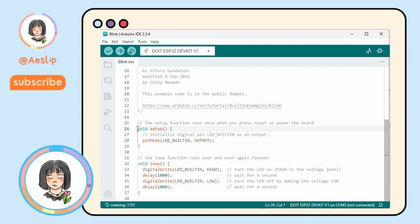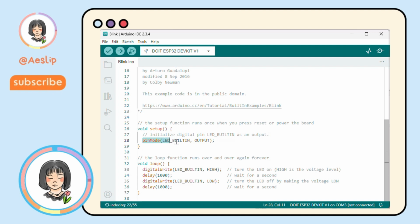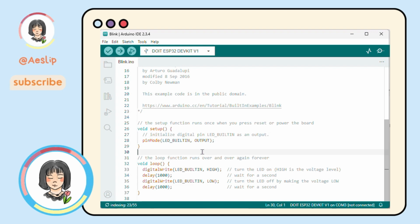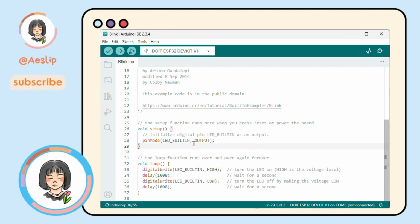First is the void setup. This function is called once when the program starts. It's where you set up the initial environment. In the void setup, we define the mode of the built-in LED pin. pinMode is a function that configures a pin to behave either as an input or an output. Here we set the built-in LED pin, usually pin 13 on many Arduino boards, to output, which means we are going to send a signal out of this pin.